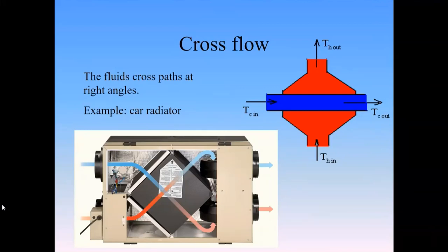We have a surface area and air can just flow through it, and there isn't really too much of a difference between where it comes in or out. We have a continuous flow in two different ways, and generally it's 90 degrees difference between the flow paths. So we call that a cross flow. And that typically would be if we have like cooling water or something like that, and we need air to pass through it, we often use a cross flow arrangement.